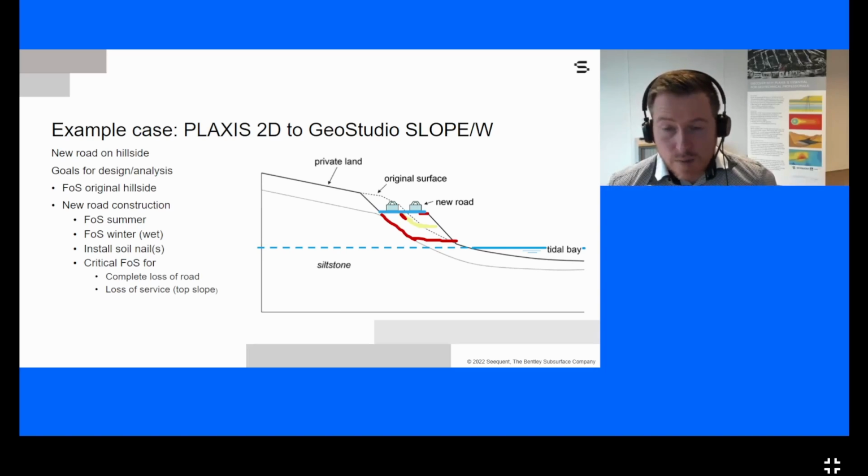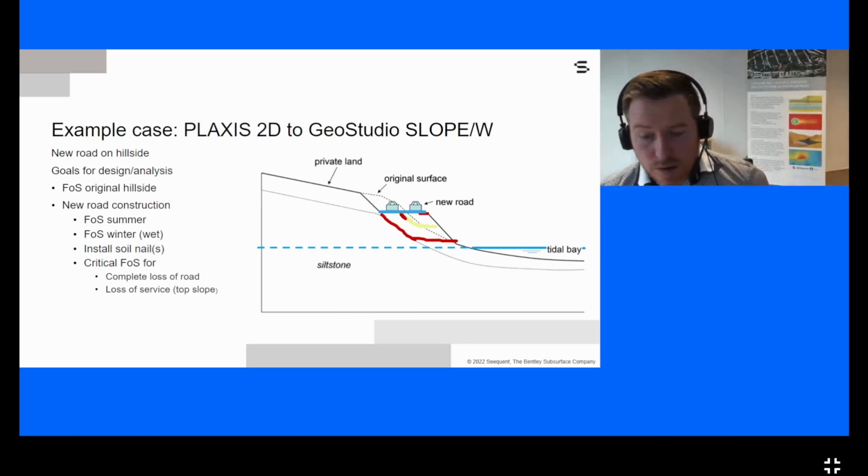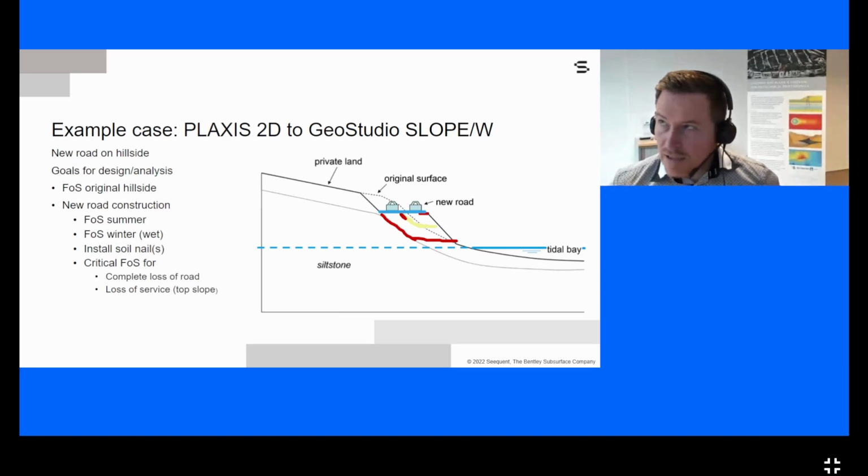Of course, you can check that by checking the skin resistance developed inside PLAXIS, both for the plastic calculation phase as for the safety analysis. You can easily judge that, but in Slope W, it will do a full mobilization of the skin resistance when determining the factor of safety. So that's something you definitely have to take into account.